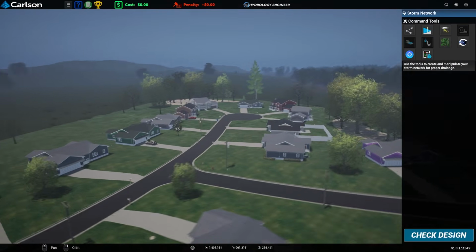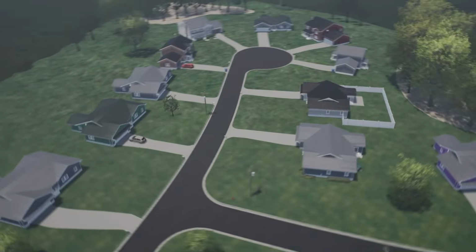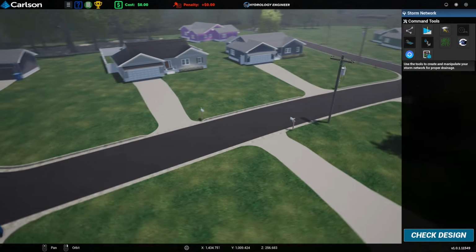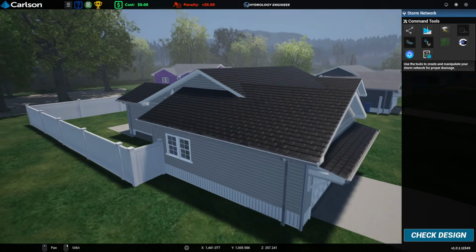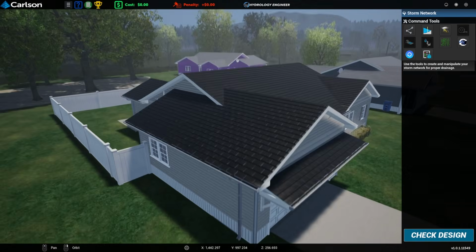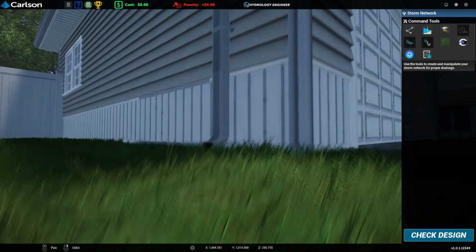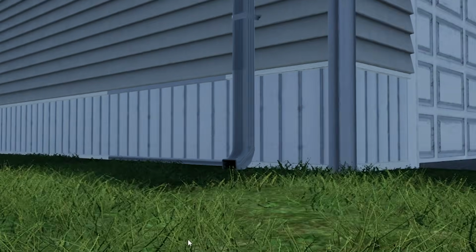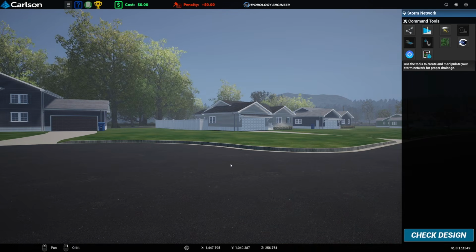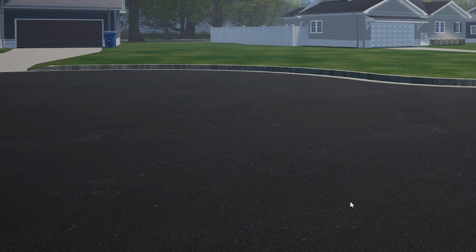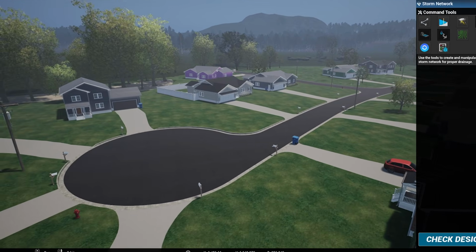So this is our new map. Oh, which I say new, it is actually the same. I think it's the same layout as previously. But yeah, we now have surfaces to deal with. We've also been told we need to drain the roofs. So these roofs have, can you see the down pipes? Basically all the water that lands on there has got to go somewhere. And if you have a look down at the bottom, can you see down here the down pipe? That just goes onto this grass, which means this grass, which I believe falls towards our road, is going to have way more water contributing towards it, which means we're probably going to need way more gullies than we had previously. Now, 2 things before we start this.